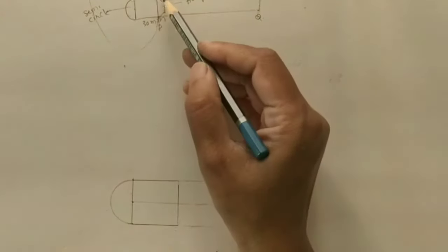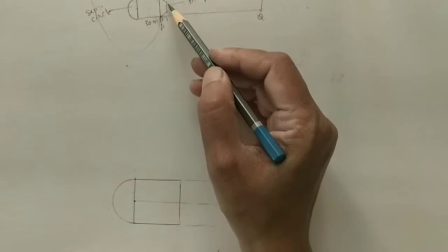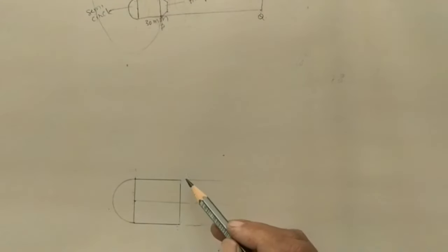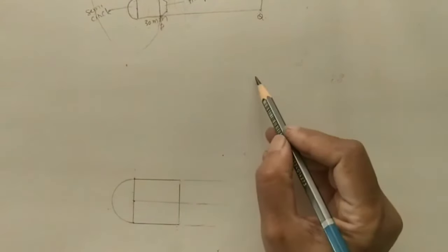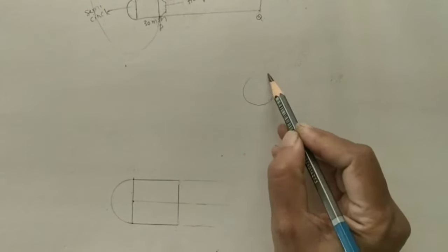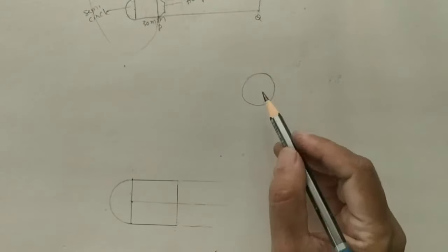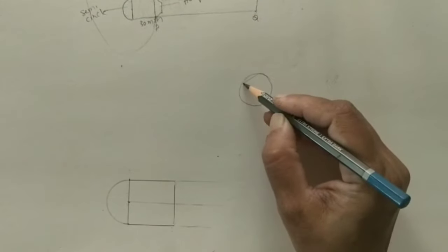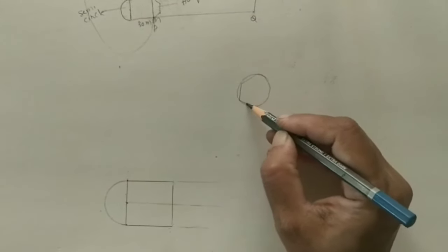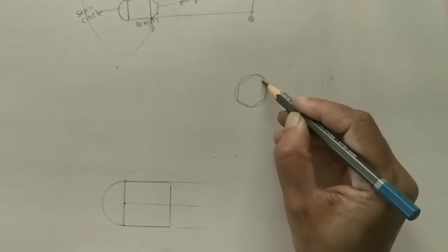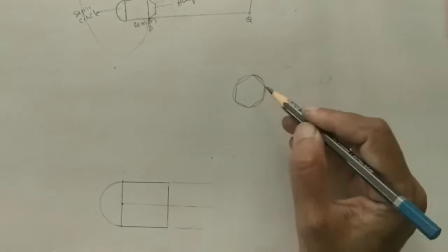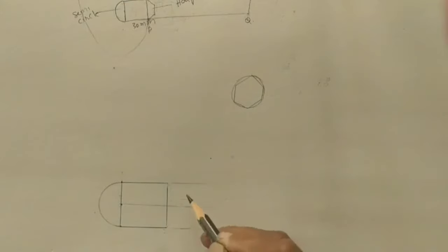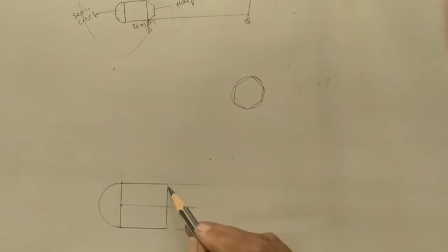Here we need to draw the hexagon. Okay, we don't know how much each side of the hexagon is. For that, I am taking one circle. There is the inscribed circle method, in which we take one circle initially and can insert the hexagon in it. Roughly I am doing it like this. One hexagon will come inside the circle. So here I will draw the circle which passes through these 2 points. It is the diameter. Okay.